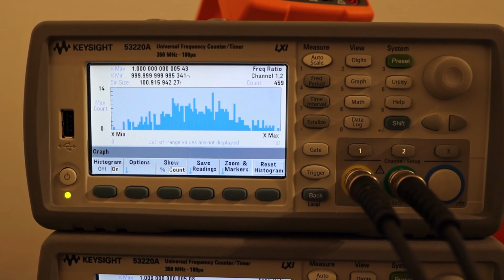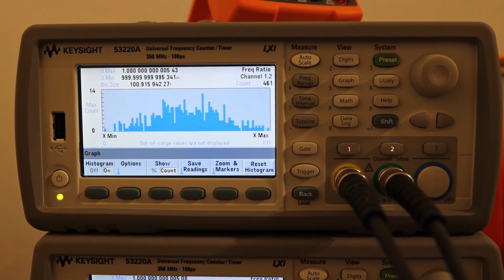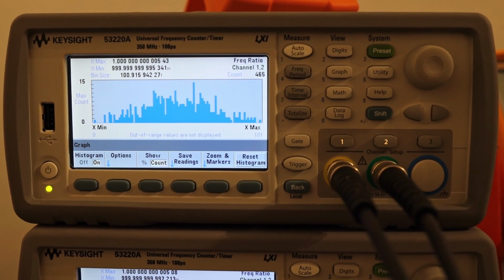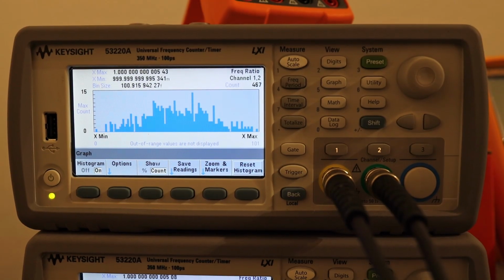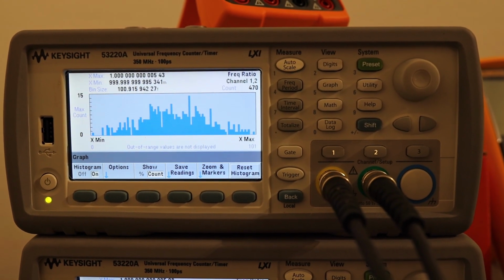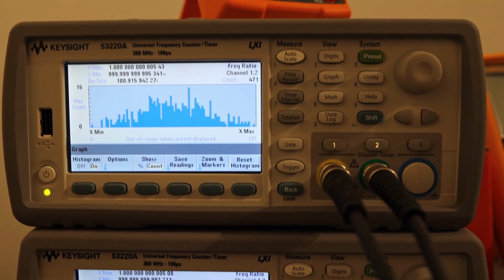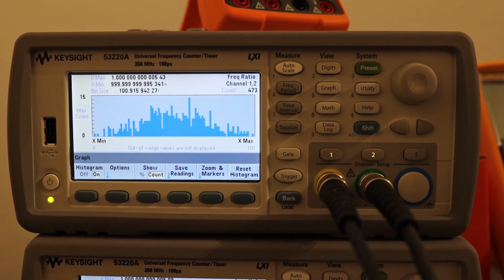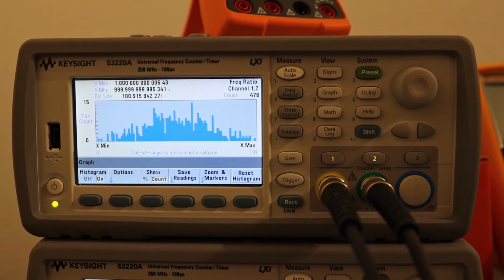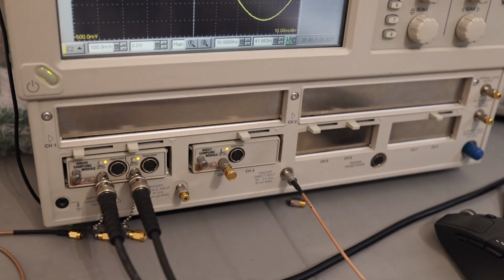Now I will show you the phase relation between two channels, and we'll go to my 50 gigahertz oscilloscope, and there I will try to do phase measurements, because the oscilloscope is only capable of very low voltages, can only display 1 volt max, so we have to limit the total input from 8 dBm to lower, so that we can get the signal frequency in range itself. So we have got our measurement setup ready.